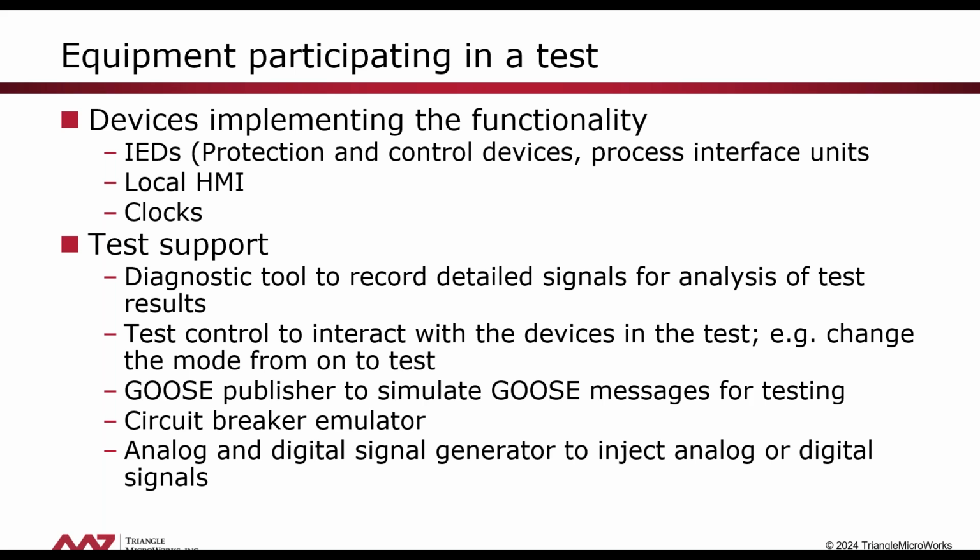But in addition, we also had a couple of pieces of equipment that we used for test support, like a diagnostic tool that recorded detailed signals for analysis of the test results later on, and test control that was able to interact with the devices in the test, as an example, changing the mode from on to test. We needed GOOSE publishers to simulate GOOSE messages for testing, circuit breaker emulators, as we didn't have physical circuit breakers connected. And then, of course, the signal generators, the test sets that we use to inject analog or digital signals based on the test.